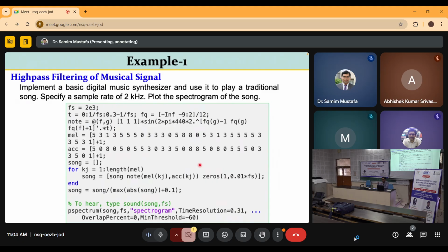So you have to eliminate the noise. For example, I gave an example yesterday of a bridge-vehicle motion, where the vehicle is moving and producing some displacement. Now this displacement has two parts: one is static, another is dynamic. Static because of the weight of the vehicle, and dynamic because of the vibration of the bridge. So I have to eliminate the dynamic part from the total response, so that only the static part due to vehicle weight remains. Then our calculation will be more accurate, right?